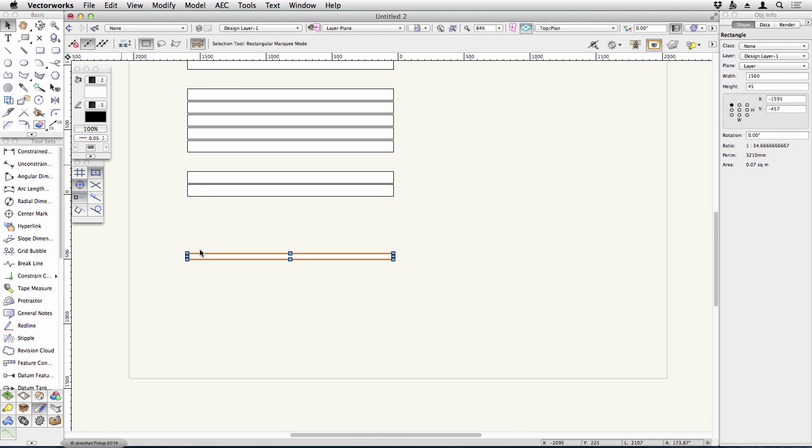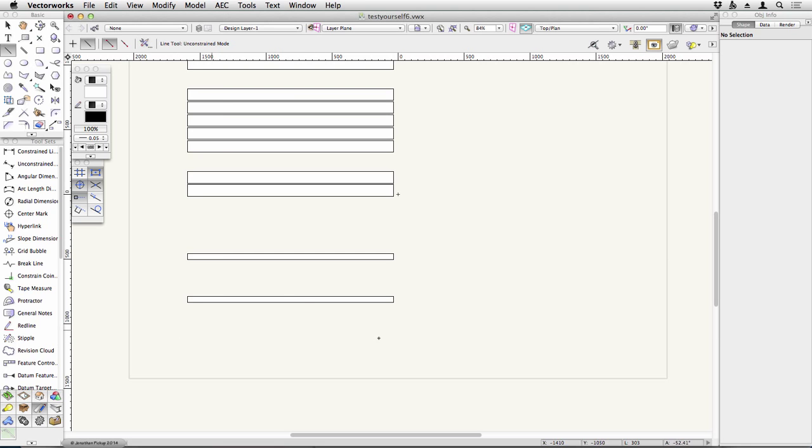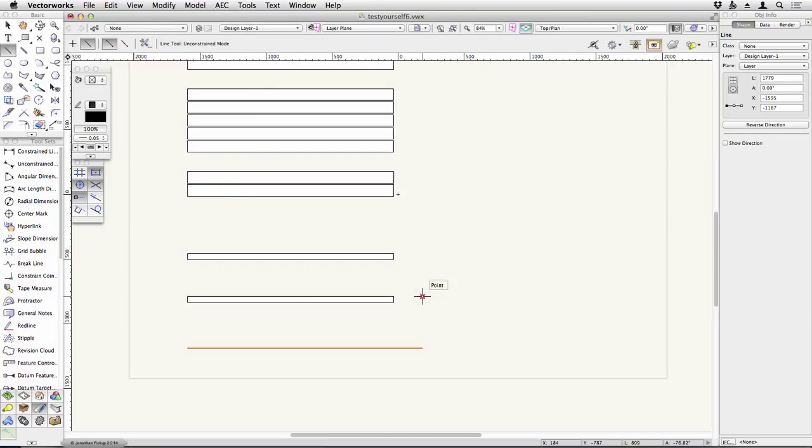The height difference between the tabletop and the table seat I know, so I can use this. I can set that back to one duplicate. So starting there and finishing minus 330 millimeters, enter once, enter again, and that's given me my seat. Now I need to have some legs down here, and if I draw the legs here, it'll help me to draw the plan part of it. I'm going to draw a temporary line to represent the ground. I know the distance there, so I can use my move command. That's minus 400 millimeters. That'll give me something that I can snap onto easily.